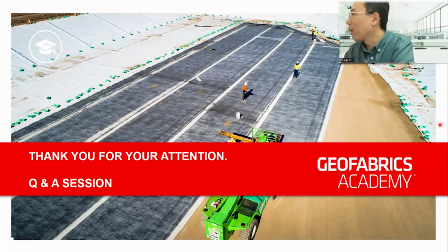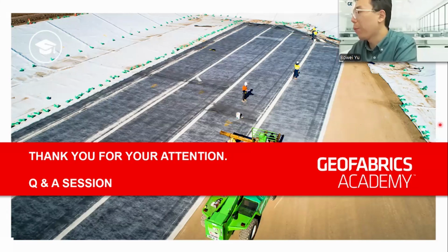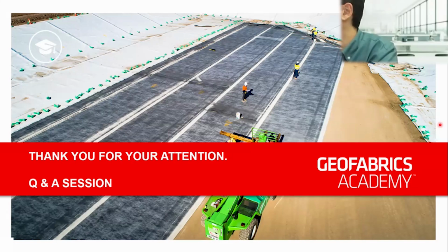And Vinod just asked, so wetting and drying, how does this affect the performance? I'm not sure what material you are talking about. If it's a GCL, it really depends. In our case, for one of our products, we have done the GCL wet-dry cycles, and currently it's reaching almost 100 wet-dry cycles. We then challenge it using the actual liquid it is going to be exposed to, in this case rainwater, and the permeability doesn't degrade much after 100 cycles.